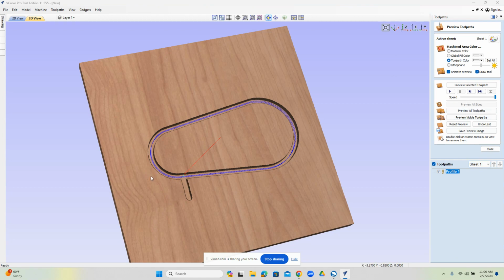One way to do it would be to have the lead off the part altogether and have it come around the shape, and then ramp off, right? And your lead you put over on the radius here, and I don't see the rest of your geometry, so I don't really know, but I would try moving it more to one of these transition locations. It really shouldn't be burning there.